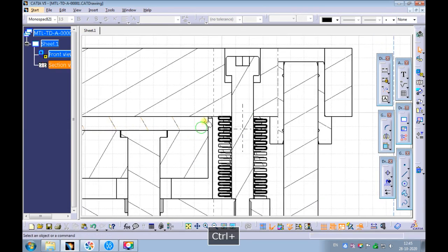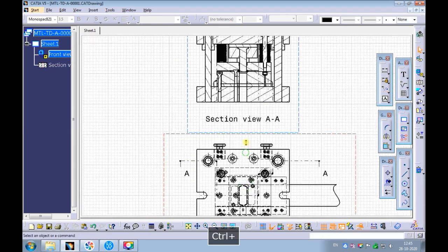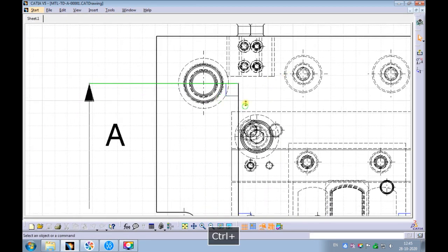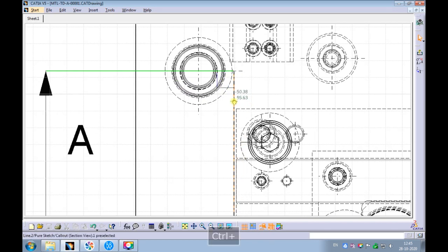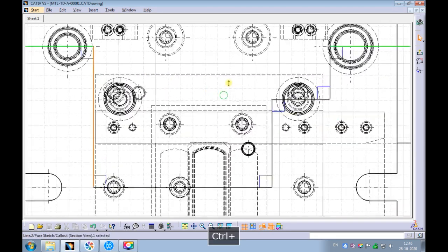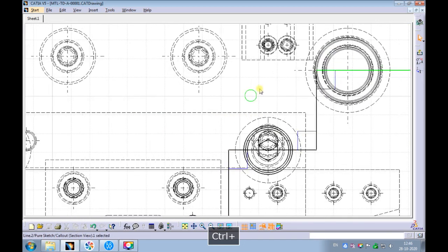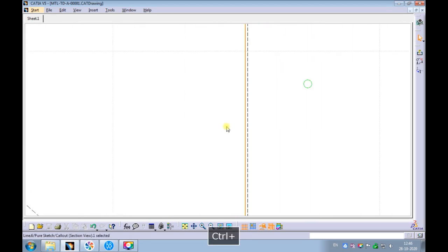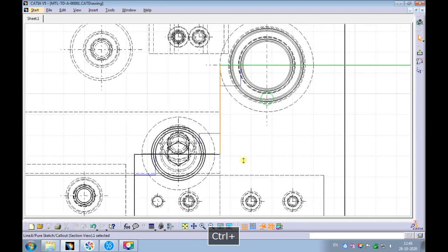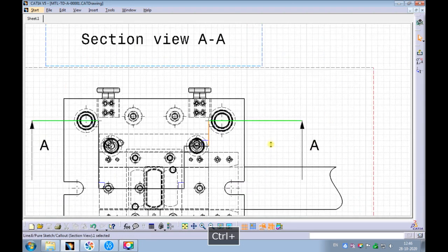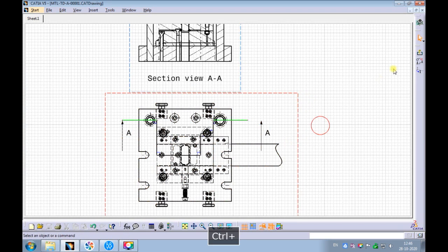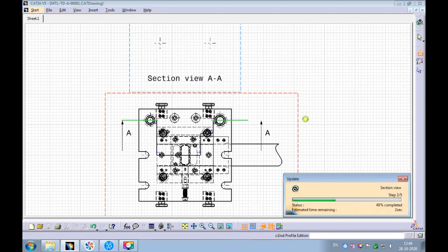Observe the position of the section profile is on the parts. Let's edit and correct the section profile. Double-click to edit the section profile. Drag the vertical lines and position them so that they are in between the parts. Click on the End Profile Addition.